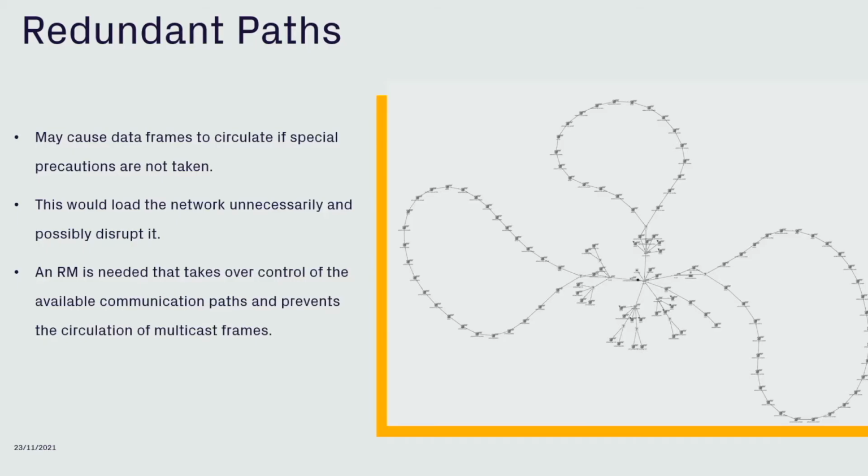Another thing with redundant paths is that you also have what you call the bus loads, line loads. Because at the beginning and at the end you have more or less communication. Later on I will have a slide about that during the diagnostics. So with redundant paths, if you have multiple rings in your network, you need to see where your rings are, and also for your diagnostics.